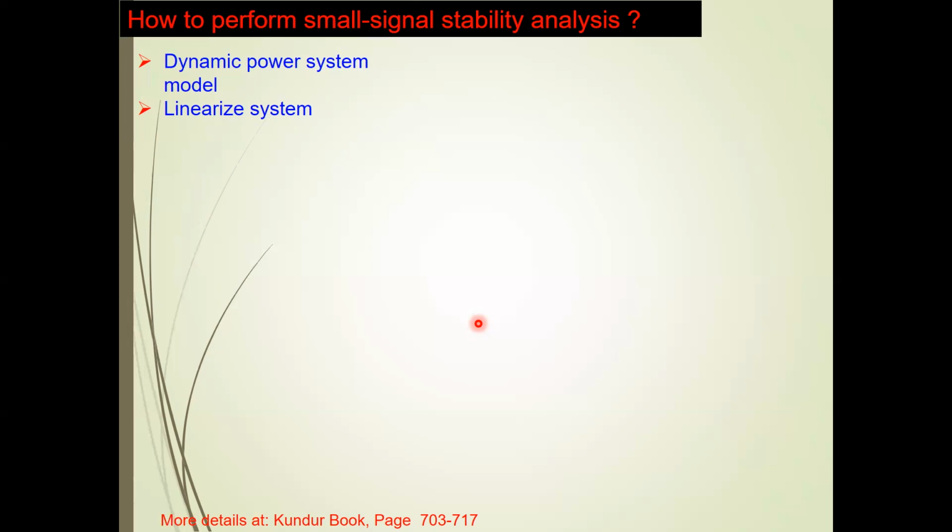Yes. So you will observe some deviation in the voltage magnitude and so on, but will the reactance change? The system parameter? No, it will be constant. That means the transformer, being a static device, will not be very dynamic in nature for a load disturbance or a line trip. Actually, I'm not talking about the fault, I'm talking about the line trip. Assuming saturation does not occur, yeah, that's fine.